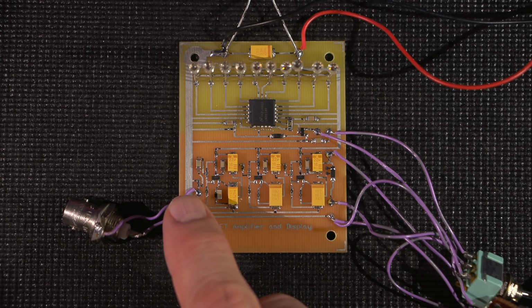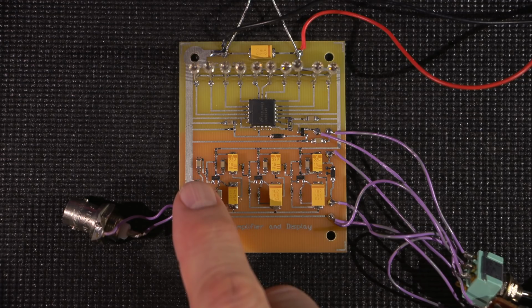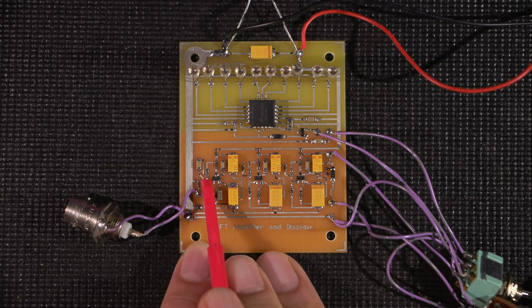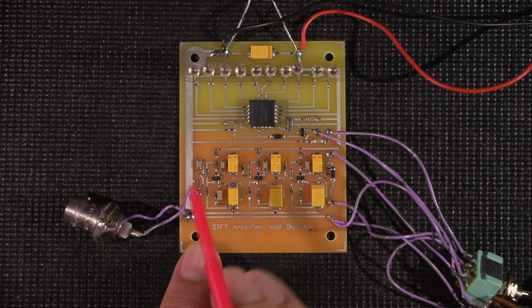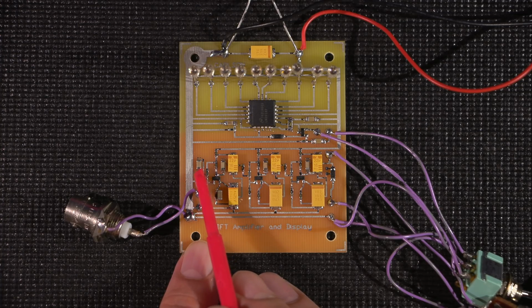So we can see that we have a trace here, we have a resistor that runs to ground. You can see that we have a trace that goes up through a ceramic capacitor and runs down to here and into this area here on the transistor. Let's grab something to point with here. Into this area right here on the transistor, this little pin right here, or leg if you like.